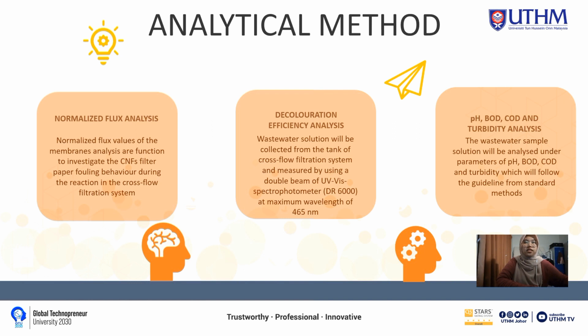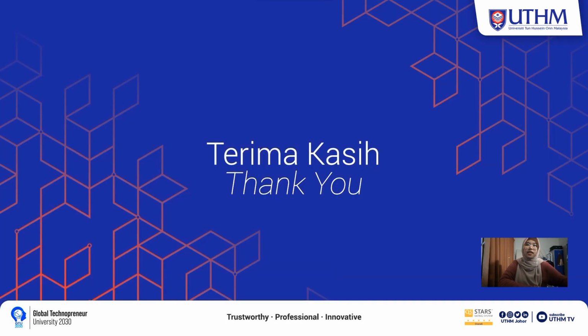For decolorization efficiency analysis, wastewater solution will be collected from the tank of the closed-flow filtration system and measured using a double beam UV-Vis spectrophotometer DR6000 at a maximum wavelength of 465 nanometers. For pH, BOD, COD and turbidity analysis, the wastewater sample solution will be analyzed following the guidelines from standard methods.